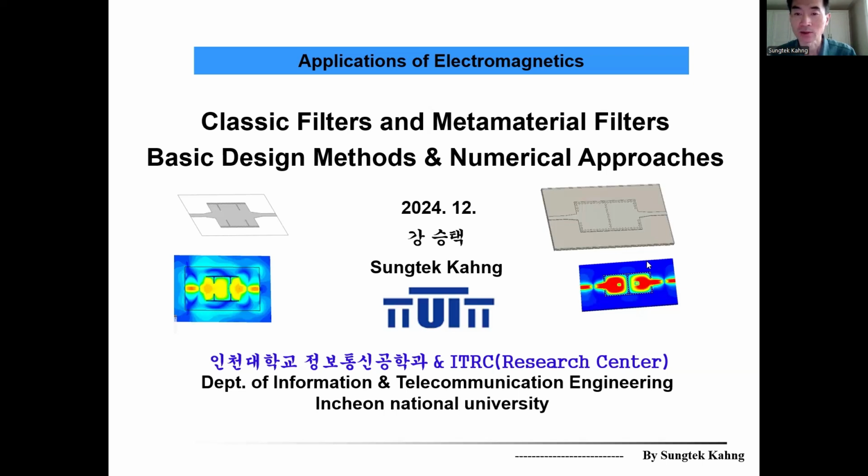On the right-hand side, at a glance, it shows you two cavities, but this consists of two dielectric layers. Underneath this top surface, there's another pair of cavities. So this is the filter shape of an SIW fourth order filter.